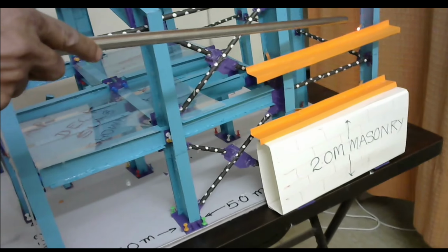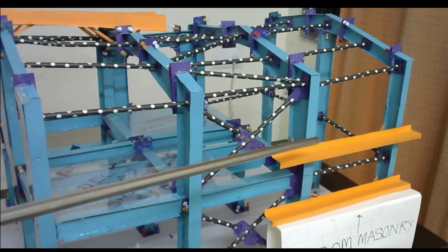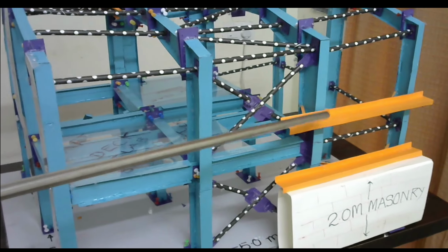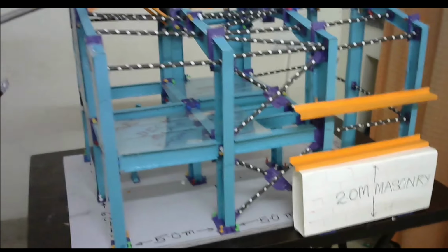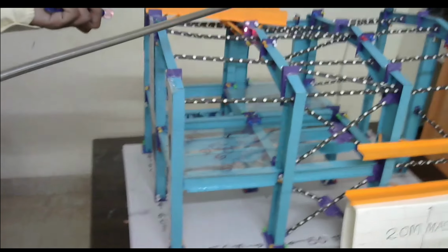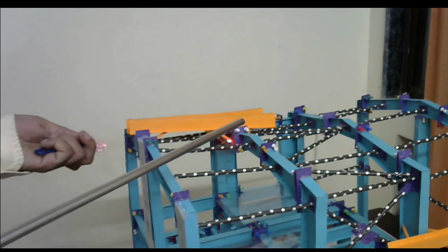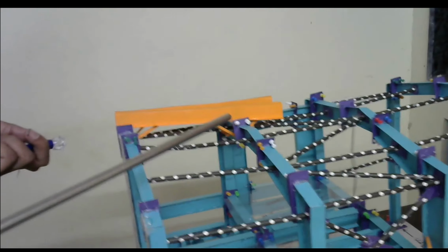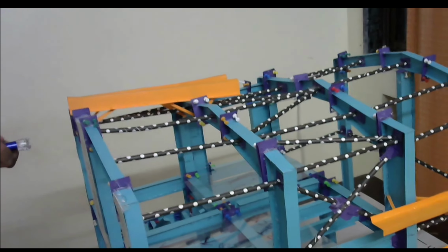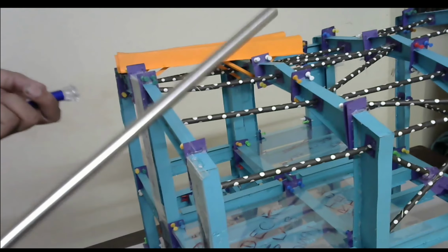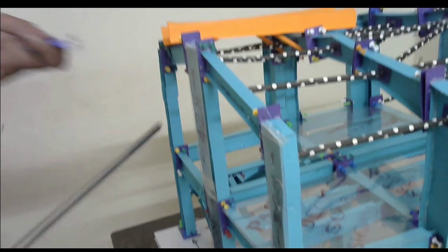The column flanges are braced through the girts using angles. These are allowed in industrial buildings, but not in commercial or residential buildings. And obviously the roof bracing, these flange braces of the rafter, the beam at the top. The roof braces are allowed in PEB buildings as well as residential or commercial buildings, because commercial buildings usually have a false ceiling, so these roof braces will be hidden. But in a commercial building, the flange bracing for the column part is usually not allowed.